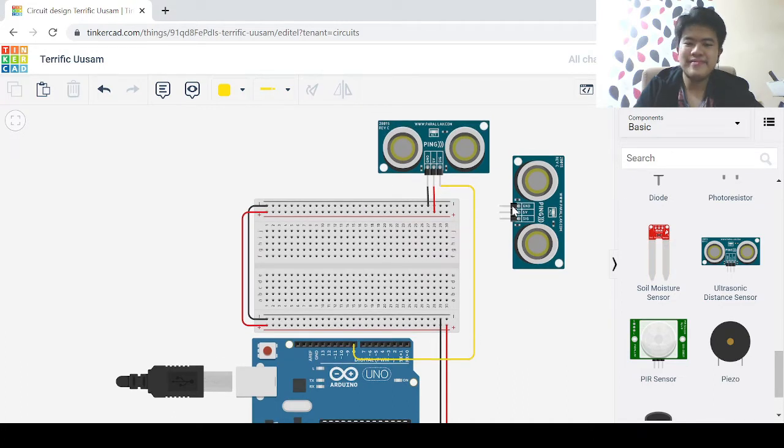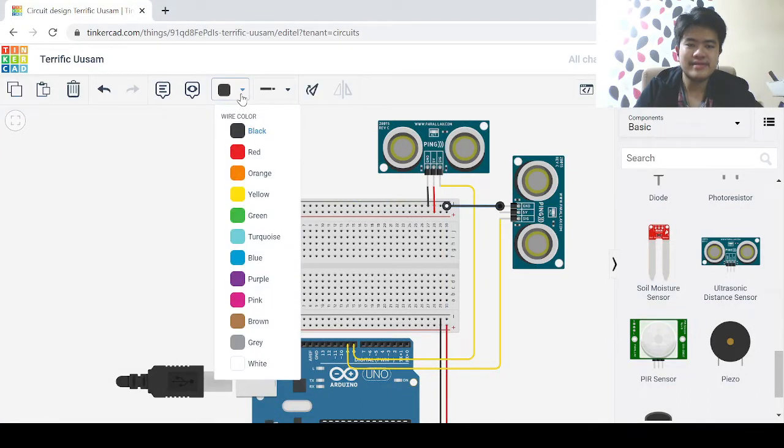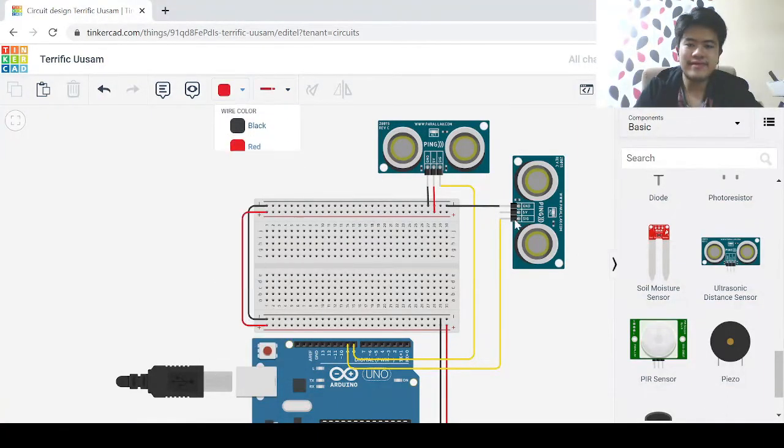As it's connected, you now connect this second ultrasonic distance sensor. You can choose any pin you want. Go to the bottom, put it a bit further, and towards D9. Then connect the rest, the 5 volts and the ground, to its respective pins. Here, put it right, the red color to the power.